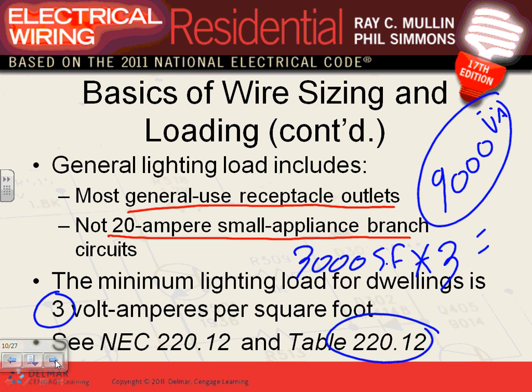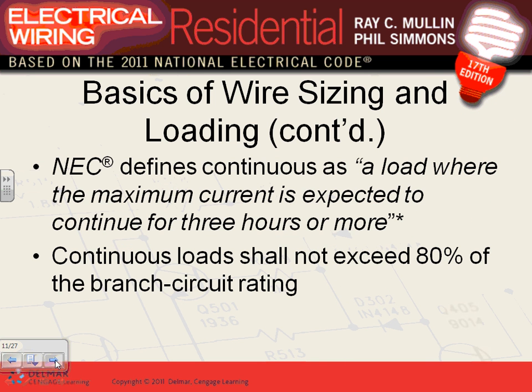Does not include a lot of things. That includes all your lights in the residence, almost all your lights, and that includes all the general purpose receptacles in the residence. Does not include the equipment and does not include the bathroom, does not include the laundry room as well as the kitchen. All this calculation is coming, guys. Any question about the load? I'm interested here in the branch circuit.